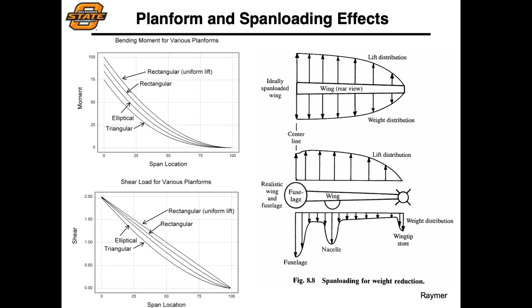So from this we're going to look at the planform span loading on the wing. So consider how that lift is being generated on the wing and what loads it's being generated under. Obviously, we have to be able to sustain lift equal to weight, but then we need a positive load factor as well as a negative load factor limit.